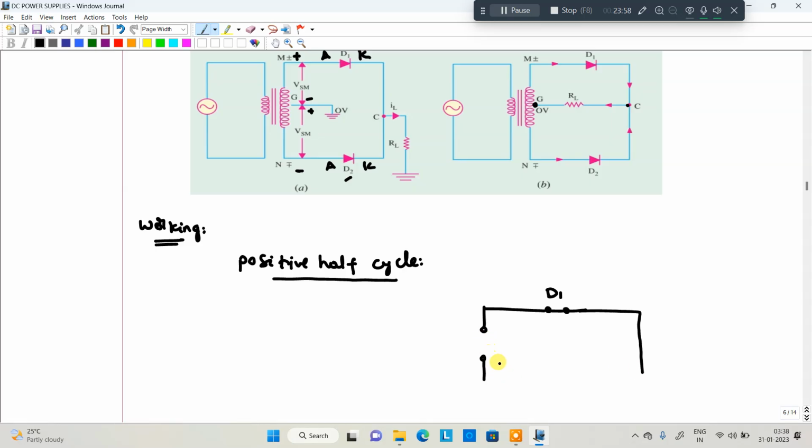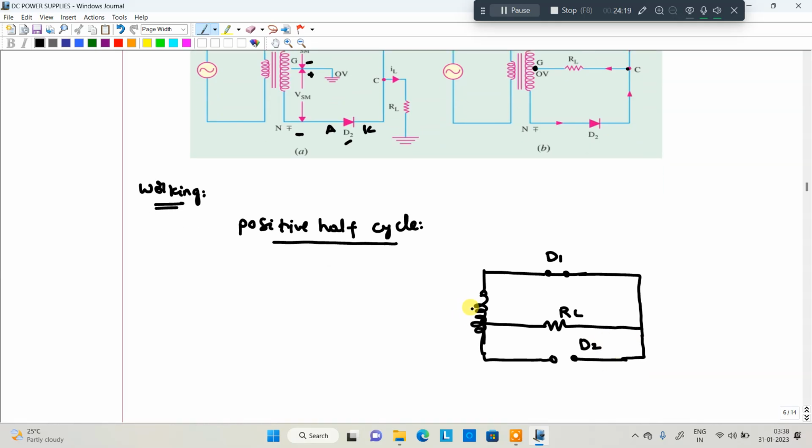In between we are connected to the supply, the middle of the transformer winding is present. In between, the resistive load is connected, that is RL. What about the output side here? In the second part of the circuit, D2 is in the off state. So this is the equivalent circuit if you are providing the Vs input voltage here.